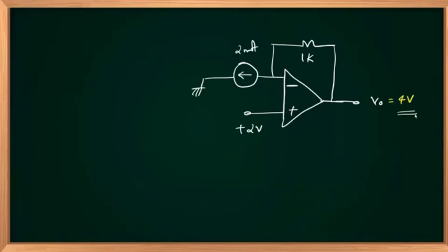Negative feedback. So V plus equal to V minus. Implies at V minus with respect to ground, you will have 2 volts, because V plus equal to V minus due to the negative feedback in the circuit. Right, and then I say 4. Okay, 4 answer I have written.